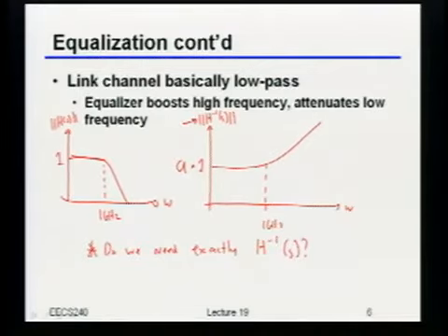So what is that kind of saying? What's also potentially okay? Roll off at high frequency. Basically, what we're going to say is, I know I can't really get gain at, say, 100 gigahertz. But as long as I get enough gain up to the point I care about, then that's probably okay. And indeed, that's actually correct.